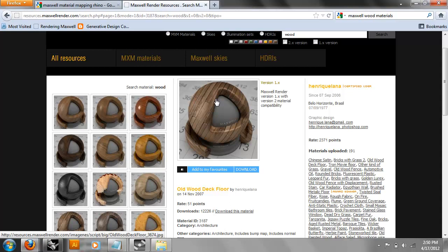What you don't want to do is apply that big piece of wrapping paper that's one sheet of concrete and wrap it around your entire building. People do that, okay? You have to pay attention to the tiling of it. Are there 4 panels on this wall, or 1 panel, or 10 panels? You don't just take one thing and apply it everywhere. So the same thing with these boards. If I applied this to a wall, it's going to look like my boards are giant sheets of plywood when I want them to be little tiny parquet boards or whatever. So scaling and tiling matter.